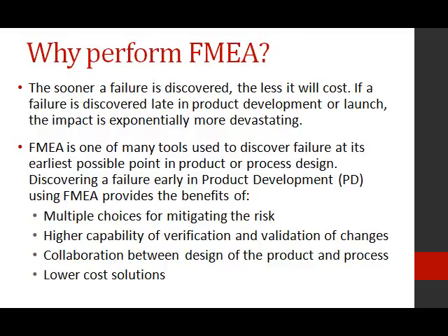Well, why perform the failure modes and effects analysis? The sooner a failure is discovered, the less it will cost. If a failure is discovered late in the product development or launch, the impact is exponentially more devastating. The failure modes and effects analysis is used to discover failures at the earliest possible point in the product or process design.